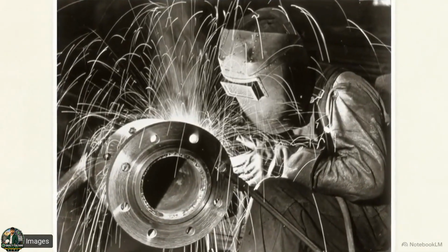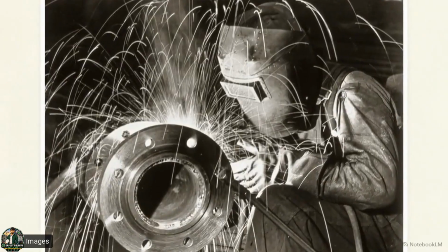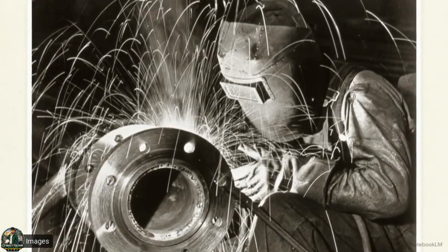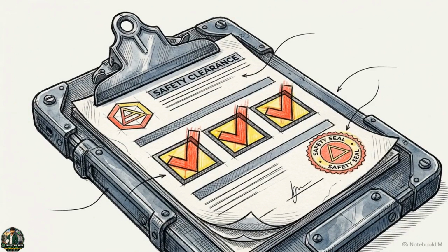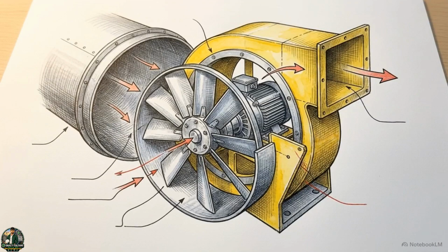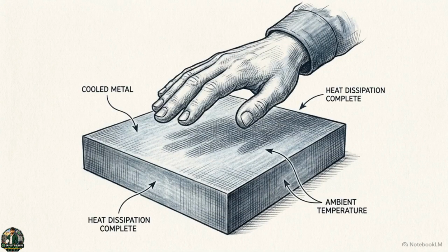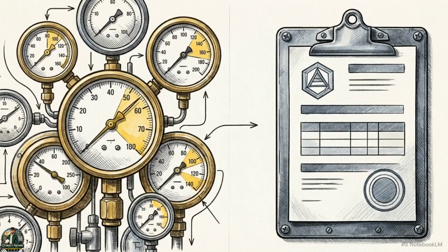It expressly prohibits any welding, brazing, or soldering on tanks that previously held flammable substances. To legally perform hot work, a facility must execute mandatory prerequisites. All residual substances must be removed, the fumes must be purged or rendered non-explosive, and the metal must be allowed to cool completely before any new volatile material is introduced. These subsections mandate that the physical properties of pressure equalization and thermodynamics be managed through non-negotiable, repeatable human operational checklists.